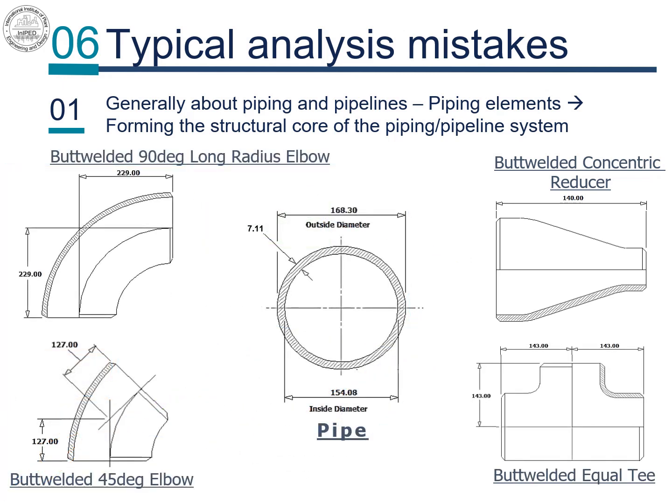So the basic general pipe route is assembled out of these elements to form the structural core of the piping system. Each of these element types are covered with different standards which are regulating their use. For example, B36.10M covers dimensions of welded and seamless wrought steel pipe for high or low temperatures and pressures. Or the B16.9, that is covering wrought butt weld fittings, for example elbows, tees and reducers.